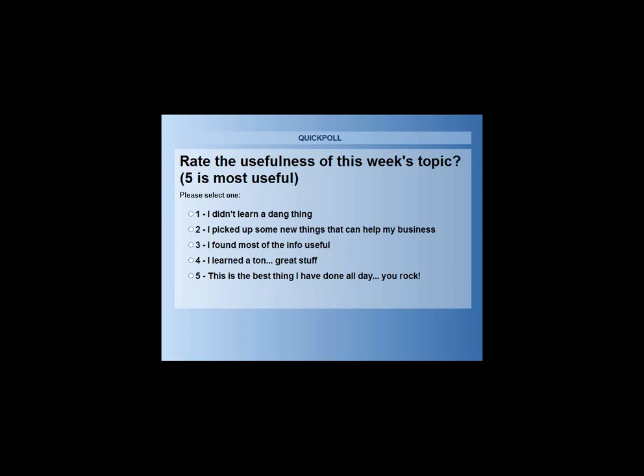Boris asks, would you suggest a VFD to reduce the CFM from a small hood exhaust fan when the sash is closed? I don't really know the answer to that, because when you say a small hood exhaust fan, I'm thinking some kind of process thing going on, so I don't want to answer that directly. However, when you say small, I think don't spend money on a VFD. I don't know how small is to you, Boris, but if things are small, probably not going to be worth the effort of retrofitting a bunch of stuff on them. I would find the big fans in the building and target those first. But I don't know the answer to your specific question about the laboratory hood you're talking about.